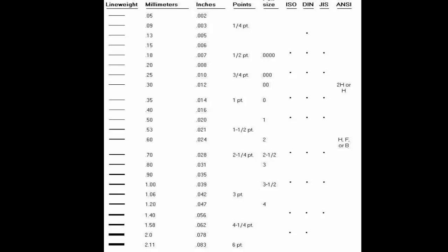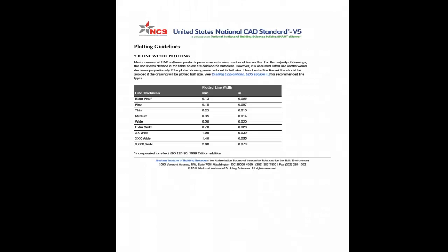And some of the things that we're going to be looking at this semester are making sure that when we put notes on a drawing, all of the notes are in the same font, they're in the same line weight, they're in the same layer on the computer, and they look consistent. So when you see one note, you know that the other note is just as important, because it's in the same line weight. Now, if I had something I really wanted to make stand out to you, we may do it a little bolder, but we'd stay with the same font, the font size. You'll see as we move through the semester that this just makes the drawing so much more professional looking, and we'll look at some examples as we move through also.